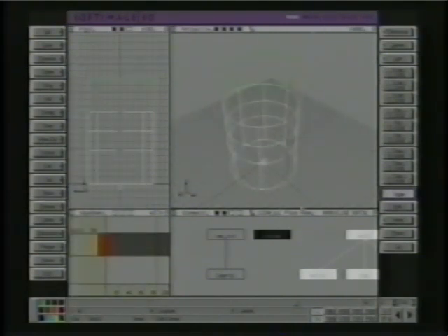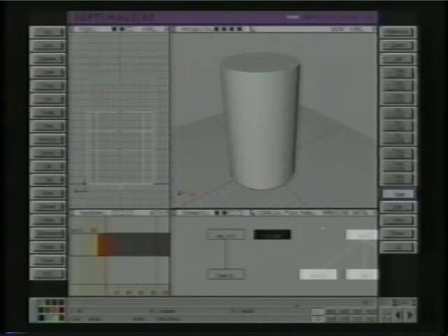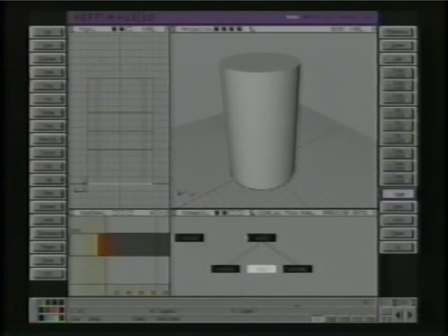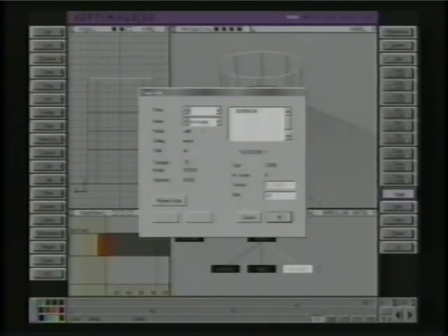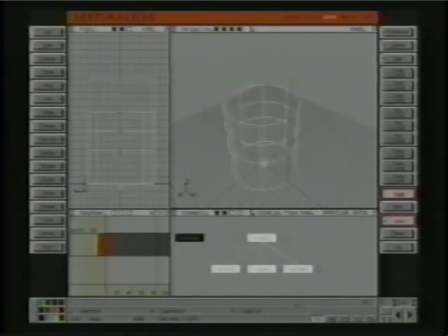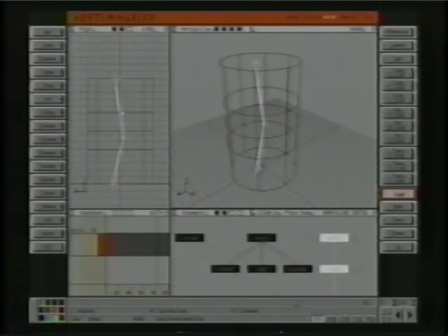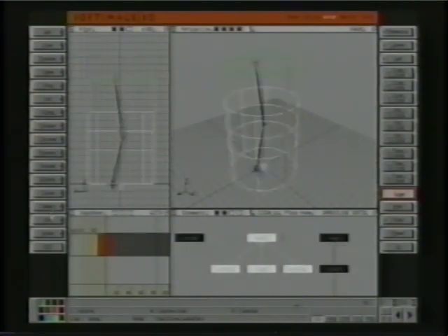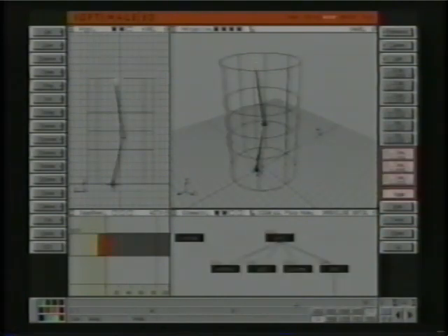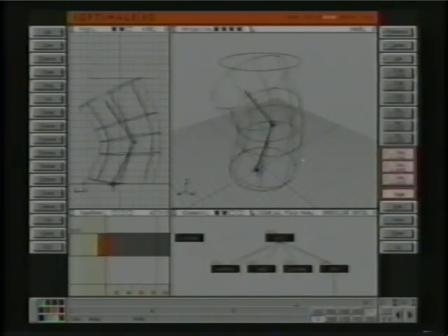Here's this object, but the way that it's capped at the top and the bottom, see this is a NURBS object, is these faces. If I do info select on them, it's a face. The problem with faces in Softimage is that they can't go in envelopes. So if I create a skeleton now, inside of here, select that, do skin, global envelope, and select the chain. And I'm going to select the effector, drag that around. See, the problem is that the face won't go with the envelope.